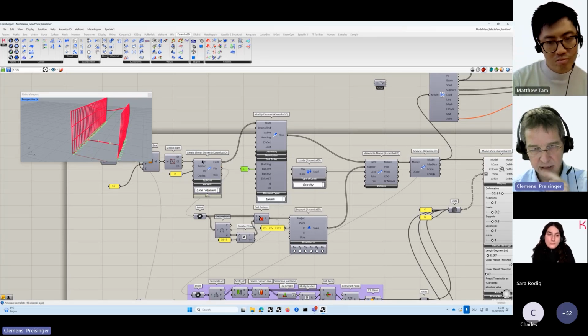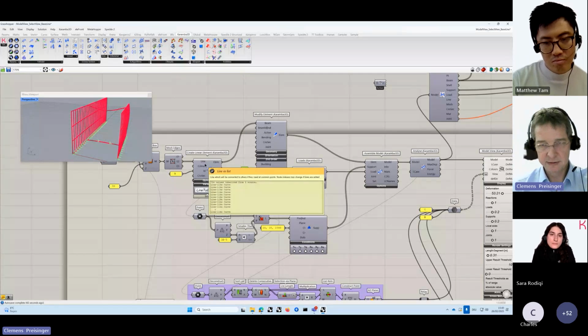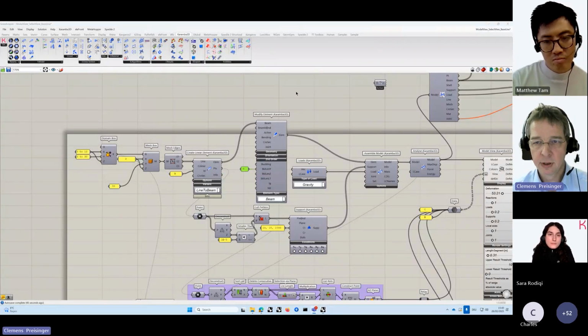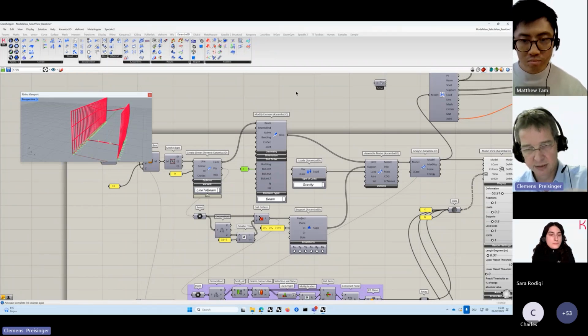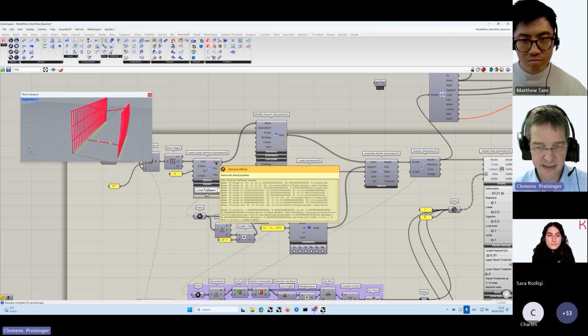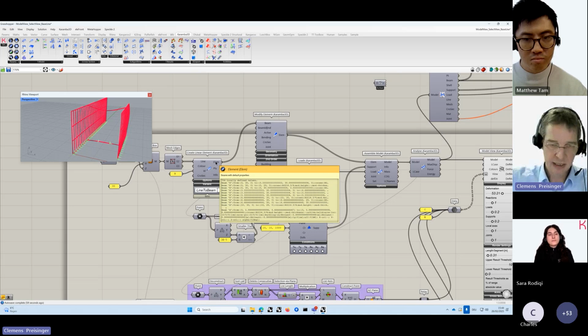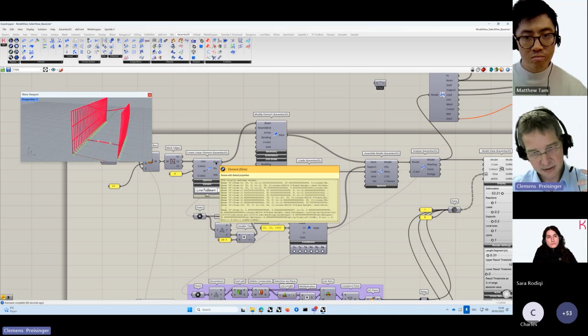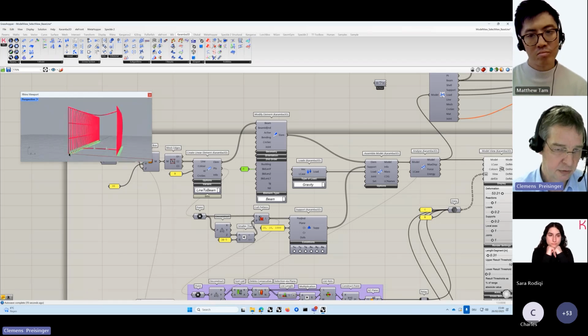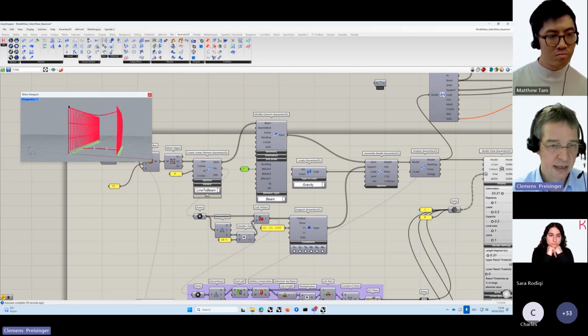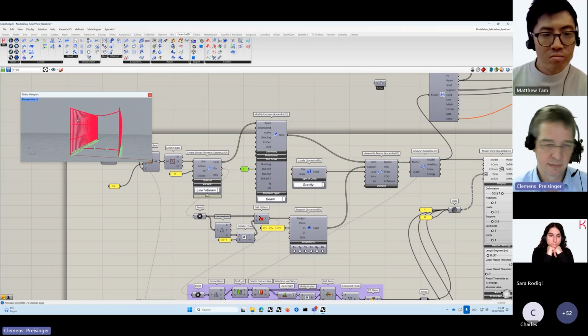And in case it's only a line, then Karamba tries to find the nodes which connect to more than two elements. So it starts here at the element and then proceeds towards the starting and end point of the element and looks for nodes which connect to more than two elements, and these nodes are then assumed to be fixed in space. So meaning in that case here, it would mean that the buckling length only goes from here to here, from here to here to here, from here to here. Can be correct, but needn't be correct.